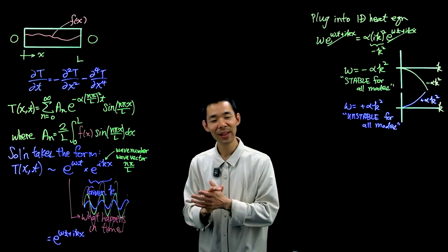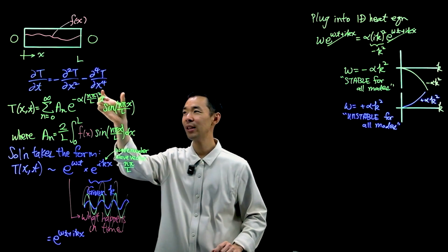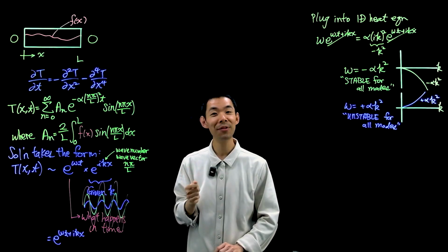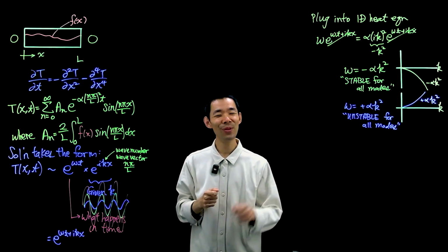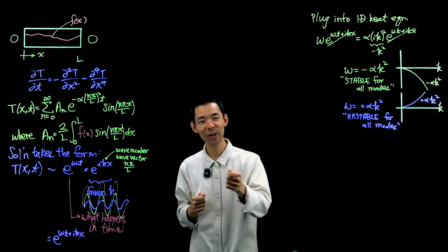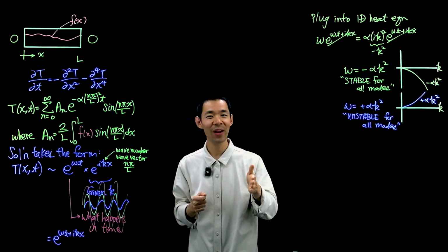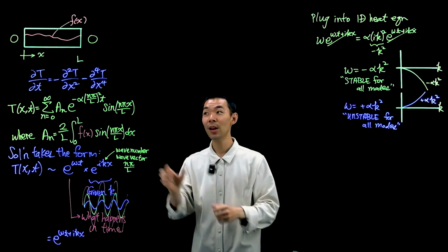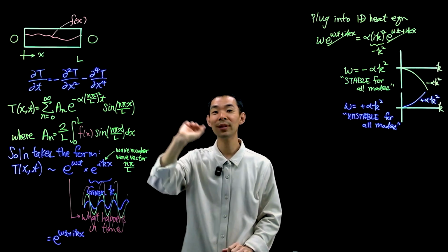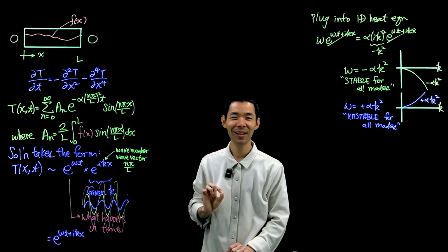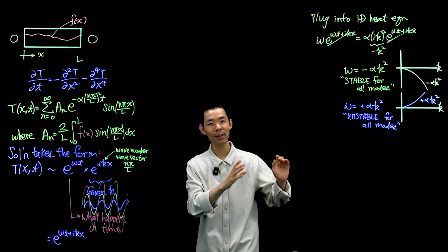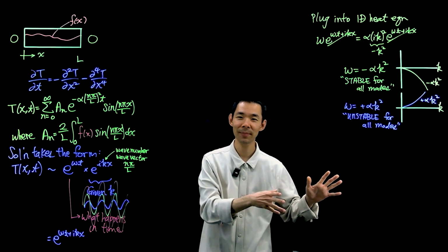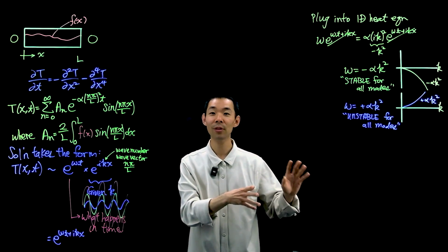Fourier's relationship, which related the heat flux to gradients in temperature, is just a linear approximation. If you expand the Taylor expansion a little bit further, so you don't clip it off at gradients in temperature only, but keep higher order gradients present, you're going to get higher order derivatives over on the right-hand side. The energy balance is a law. That is a fundamental equation of physics. But you need a constitutive relation to close that equation.